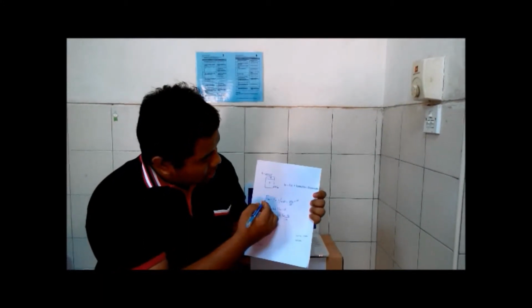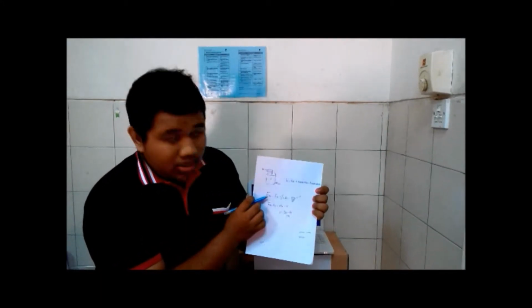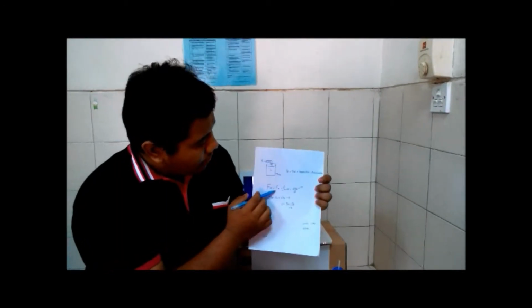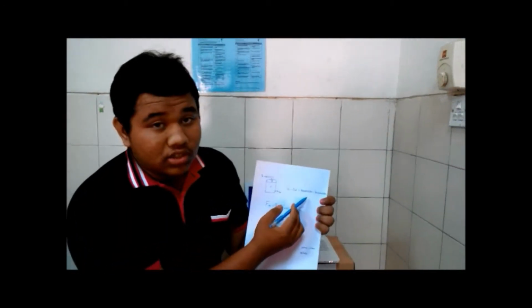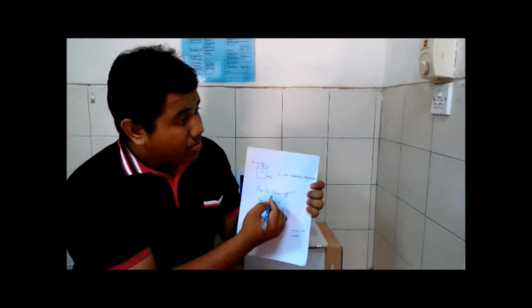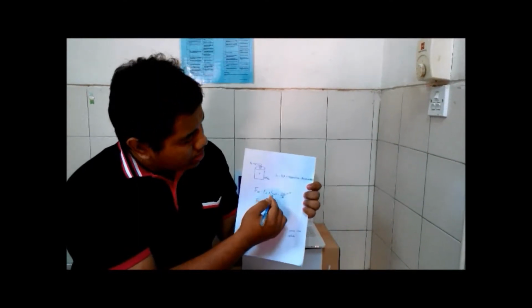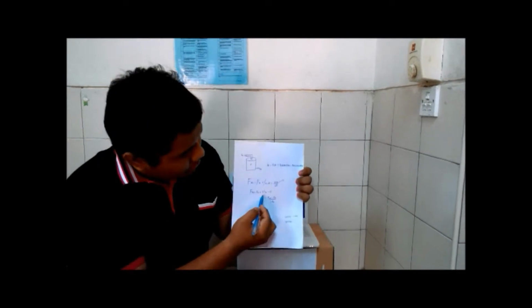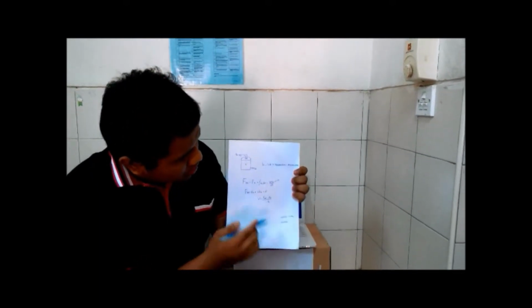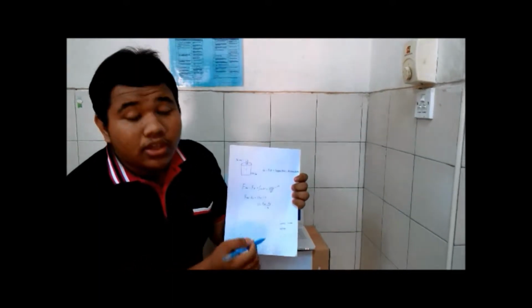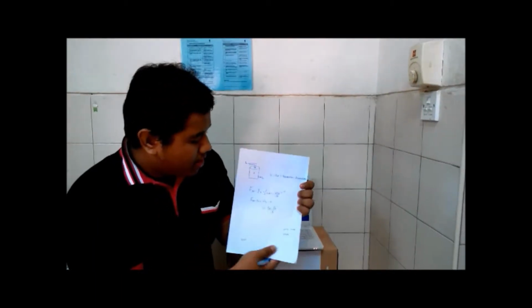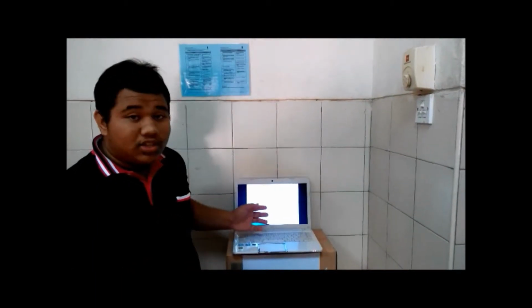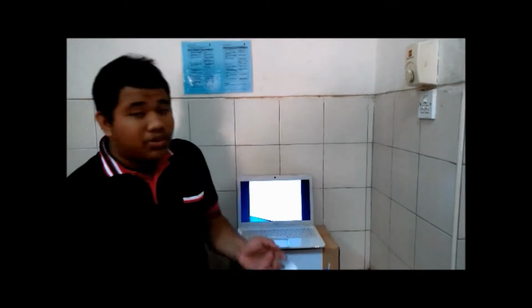And then we have F_A0 that is in, and F_A is out plus generation. Then we do the algebraic expression and find the volume equal to F_A0 minus F_A divided by negative r_A. This is the last equation that we got.